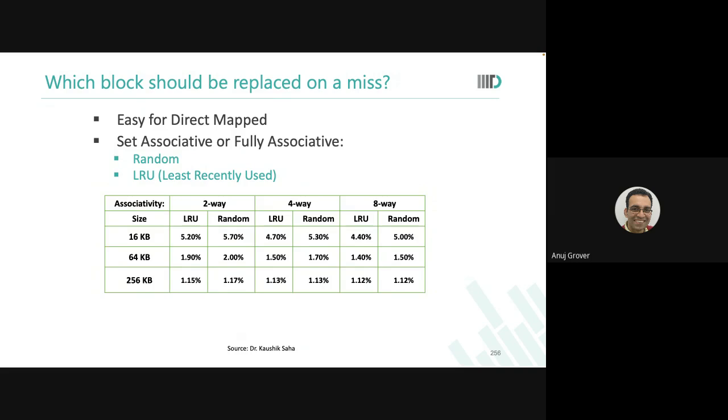So in hardware, how can you implement something that is random? He's asking, how do you implement something like random in hardware? It could be done in many ways. For example, there are these physically unclonable functions which generate a random signature, but that random signature is constant. So such physically unclonable functions are random but fixed and are also used for security purposes.